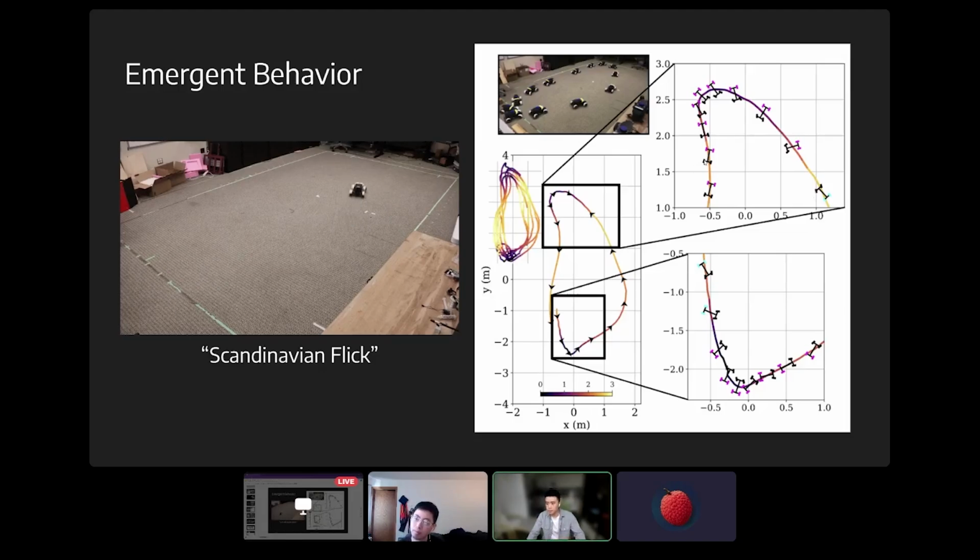So the combination of the wobble and the cold wheels, or cutting the throttle, destabilizes the robot and allows it to actually turn and start drifting, so that the wheels actually swing outside of the turn. And basically, it allows it to turn much faster. So now that the wheels are on the outside, the robot can throttle through this, or basically, as you and I would know it, it's a drift.